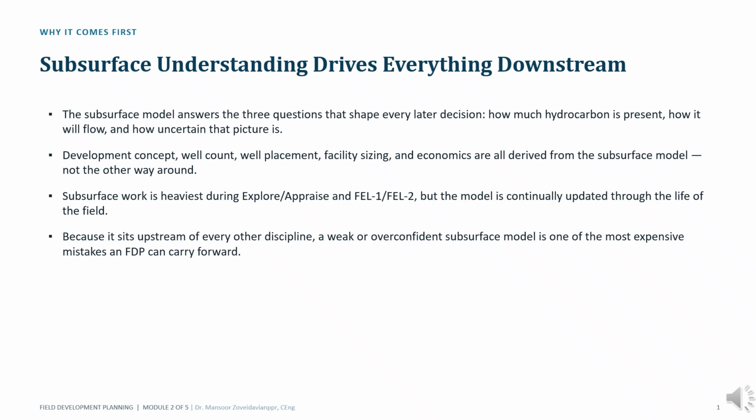Notice the direction of influence. The development concept does not determine the reservoir. The reservoir determines the development concept. Most of the subsurface work occurs during exploration, appraisal, and the early FEL stages. However, the model continues to evolve throughout the life of the field as new data becomes available. A useful way to think about the subsurface model is as the source of truth for the entire FDP. If that source of truth is wrong or overly optimistic, every downstream decision will be affected.